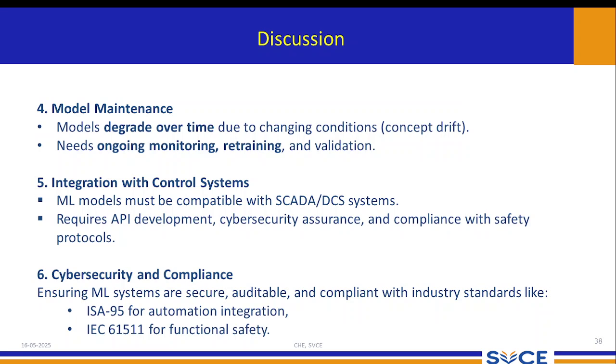Communication network: the network facilitates data transmission between the RTUs, remote terminal units, and the central server. Central server receives, processes and analyzes the data from the field devices. Human machine interface software allows operators to visualize the data, interact with the system, and control the process.